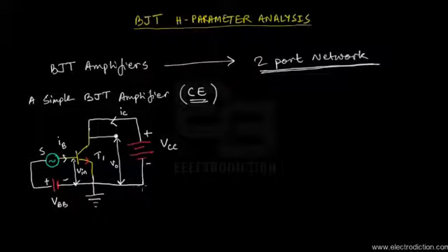So what happens here is that in order to amplify this particular signal coming from the signal source S, which is of course an AC signal, we need to set up the BJT circuit with all the biasing voltage sources, which are actually DC voltage sources, so that the amplification can take place.